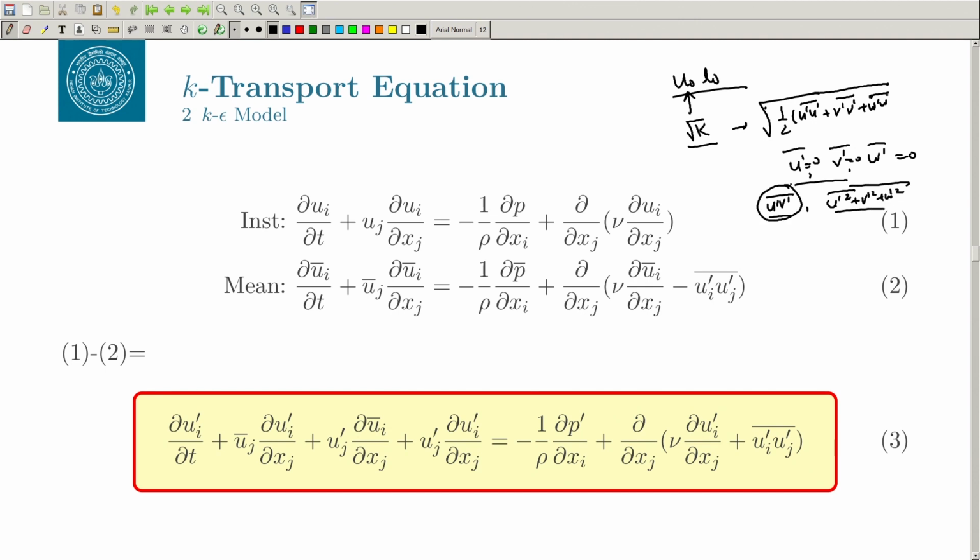And how do you get that? Basically, you take the eddy viscosity and relate it to the mean flow gradient, and you can calculate all these parameters. So you can get the turbulence kinetic energy, you can get the stresses, but not the individual fluctuations. If you are doing LES or DNS, you do not solve the mean flow equation, but you solve the exact Navier-Stokes equation. In those cases, you get the fluctuations.